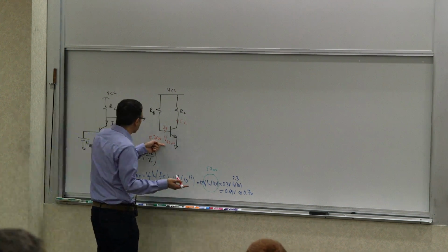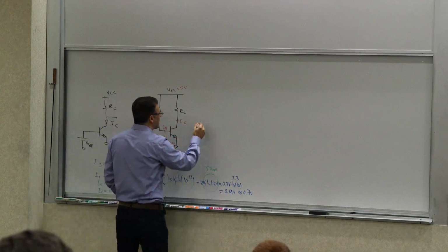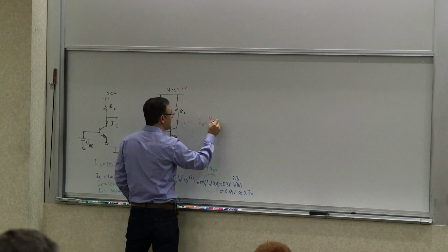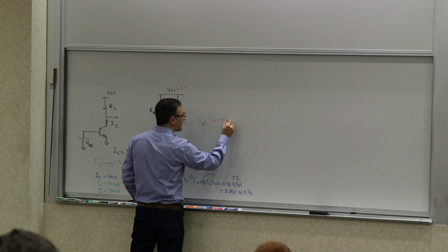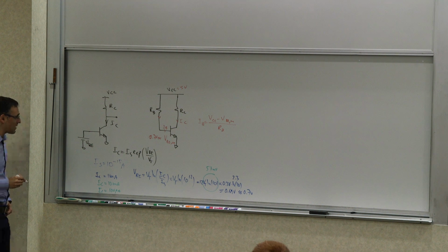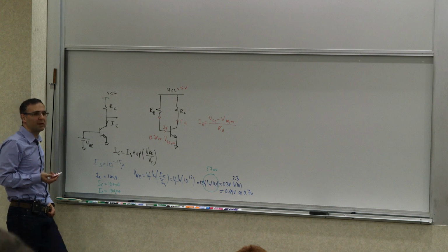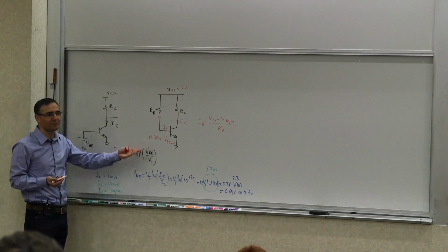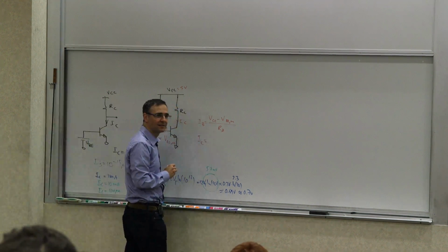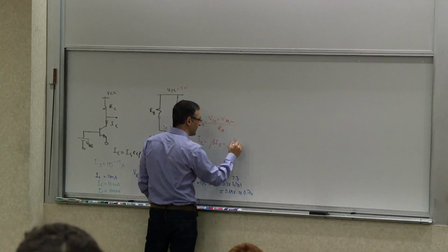So now let's go back to this thing. If this is 0.7 volt, this is, let's say, 5 volts. So whatever it is, right? Let's call it, what is this current? That current, IB, is going to be VCC minus VBE on, 0.7 volts, divided by RB. So that determines my IB. So it seems that IB is reasonably defined. Yes, it's related to the VCC, and it's determined by a resistor, but it doesn't have this horrible exponential dependence. But the problem is that the current that you really care about is IC, which is beta IB. So it has a beta dependence.